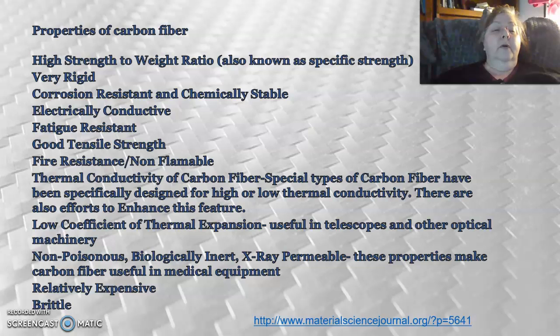Properties of carbon fiber. High strength to weight ratio, also known as specific strength, very rigid, corrosion resistant, and chemically stable. Electrically conductive, fatigue resistant, good tensile strength, fire resistant, non-flammable. Thermal conductivity of carbon fiber. Special types of carbon fiber have been specifically designed for high or low thermal conductivity. There are also efforts to enhance this feature.